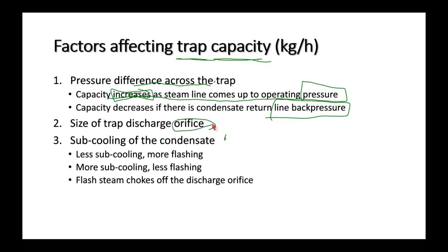Now, as for the discharge orifice, when we purchase a new trap or replacement trap, usually there's that information in there, and you may have a selection of several different sizes of orifice depending upon how much condensate you need to discharge per unit time.